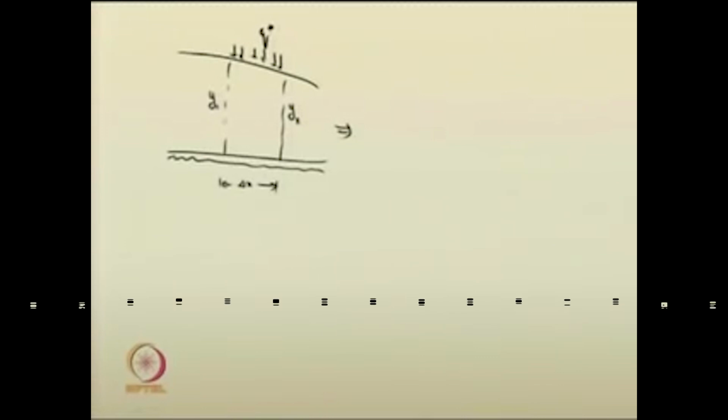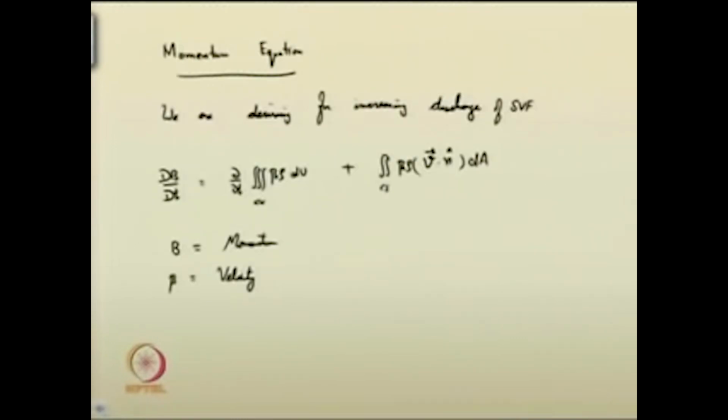This is the bed slope. Let the depth be y1 at section 1-1 and y2 at section 2-2. They are separated by a del x. This is the control volume we suggested earlier. We are having an increasing discharge at rate q star per unit length. So, the net outflow according to this equation.